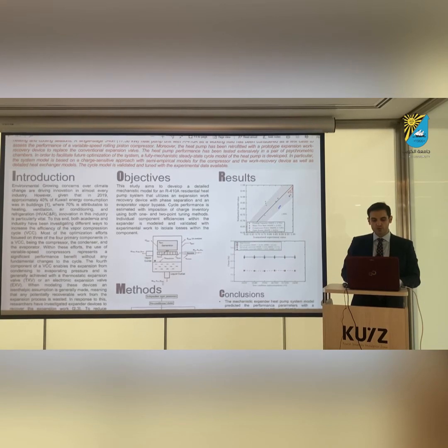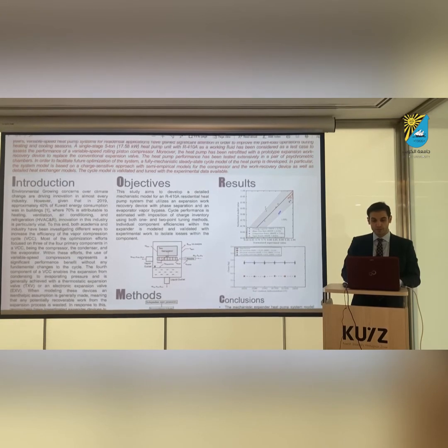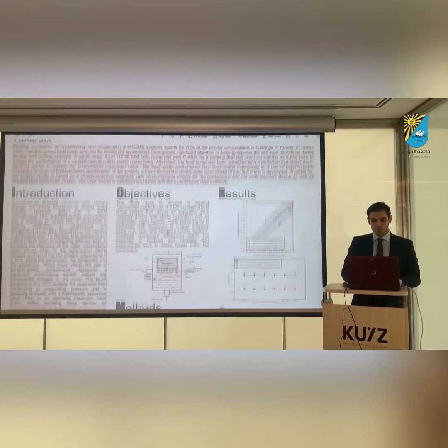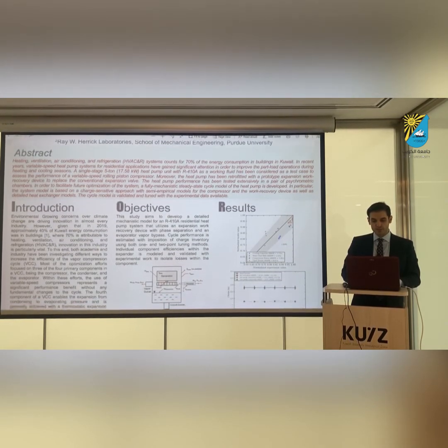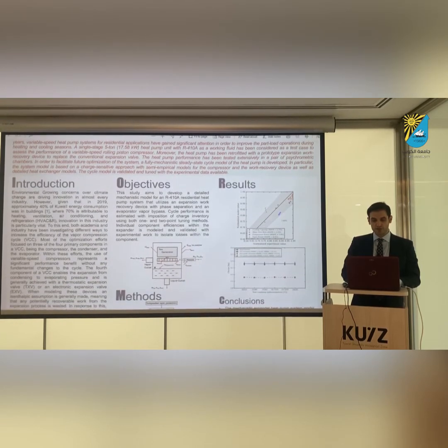The liquid goes to the evaporator, so we're flooding the evaporator. At the same time, the gas is bypassed into the exit of the evaporator. As we inject refrigerant through the nozzle, the turbine rotates